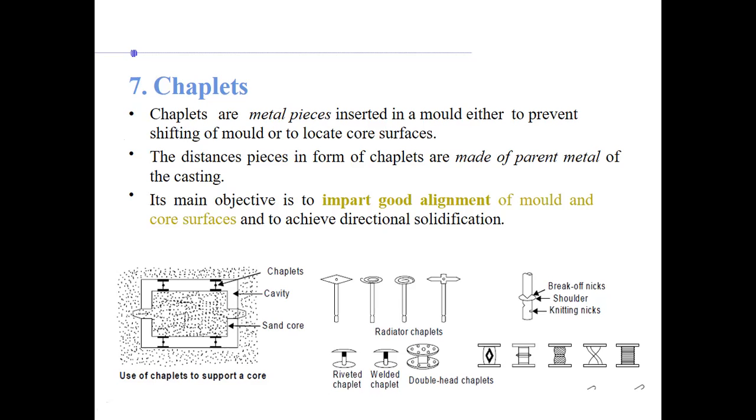So all the molten metal which is surrounding the chaplets will experience a decrease of temperature faster than the molten metal which is away from the chaplets. Right? I hope I'm clear with the point. This molten metal would solidify early because it has to give energy, or precisely thermal energy, to these chaplets for them to melt, right?